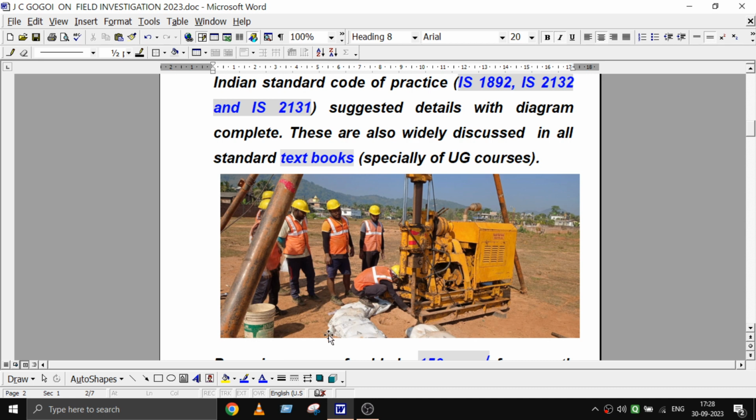So even in thickly built up areas, if it is surrounded by sufficient buildings, then percussion drilling may produce some effect on the nearest structures too. I therefore suggest that percussion drilling should not be used for boring or drilling operations for investigation purposes.